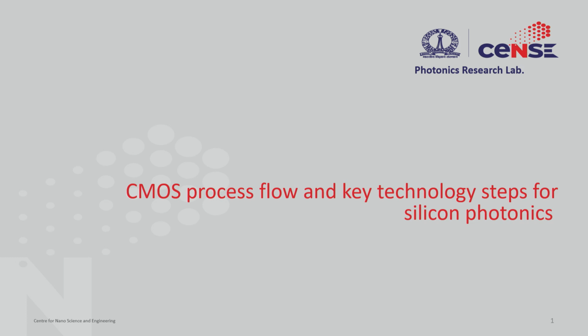In this lecture, we are going to look at a case study of how to use the unit processes that we discussed throughout the lecture and use it for some application. In this case, we are going to exploit CMOS compatible fabrication processes for doing photonics, in particular silicon photonics. So here we are going to look at CMOS process flows and key technology steps that are required to realize a silicon photonics application.